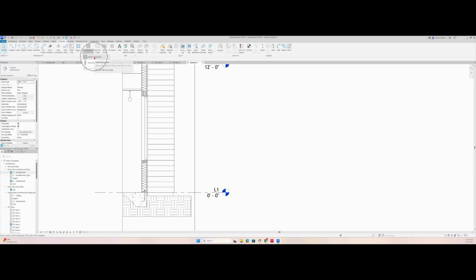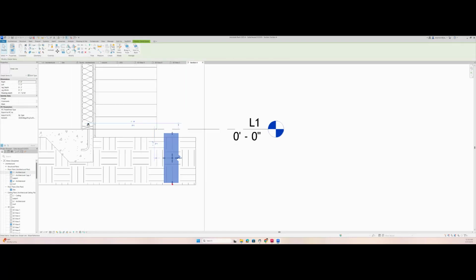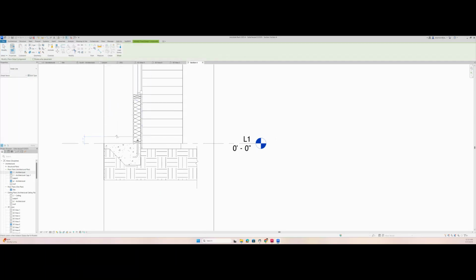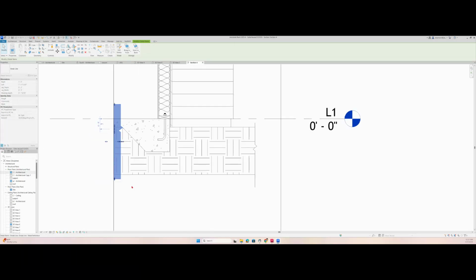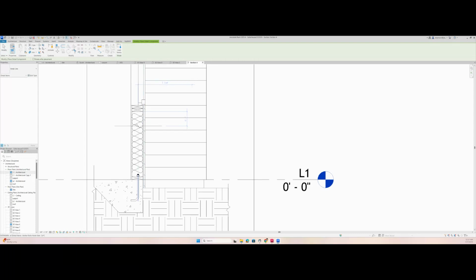Then you go to annotate and get that component, the detail component, and then guess what? You got your break line. So I'm gonna apply it here. And with those arrows, number one, I'm gonna flip it, and I'm gonna just do this because it has a nice masking region there, right? So I'm gonna apply another one here. Okay, and now think that you're applying this one here. I'm gonna apply it again here on the top. There we go, right? But I'm gonna rotate it